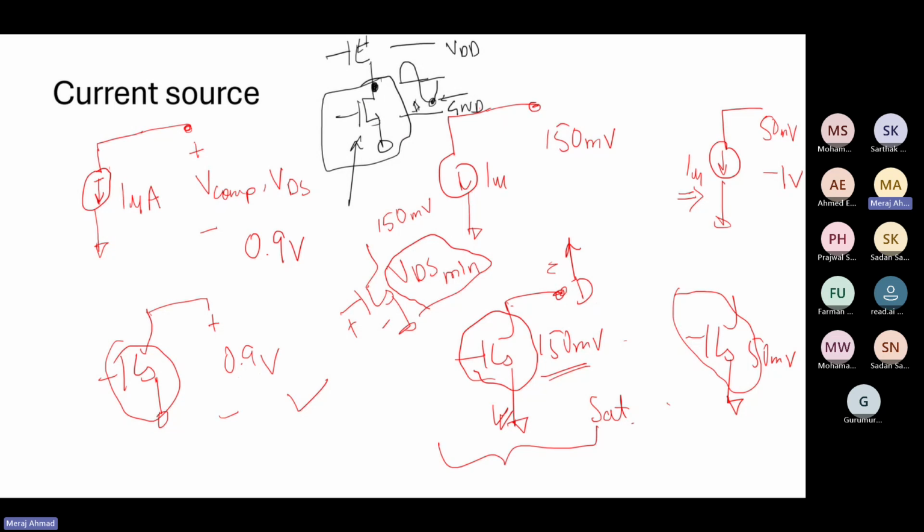in saturation. Whenever you have an output stage, if you see any datasheet, it always talks about some margin we should keep. Your output cannot reach rail to rail. For rail to rail, you need to design in a different way. But this is one of the assumptions: we need to keep VDS as low as possible so that even with high swing, this remains in saturation. Is this clear till this point?